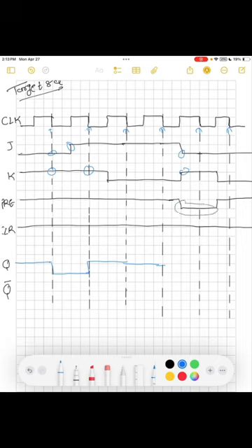When the pre is low, pre is an asynchronous input. It overrides the clock and forces Q to 1 immediately without waiting for the clock edge. So Q has to become 0, but pre takes part, so it remains 1.